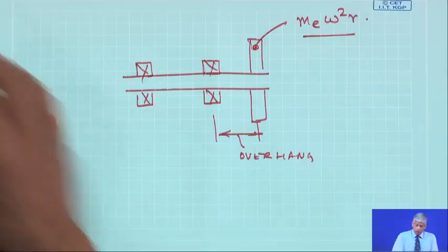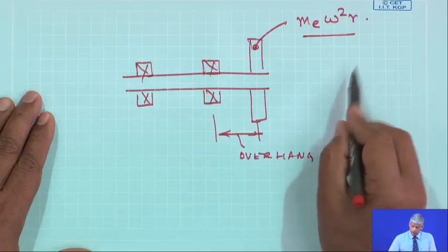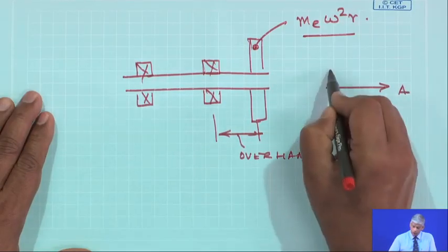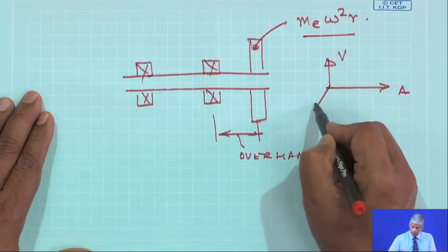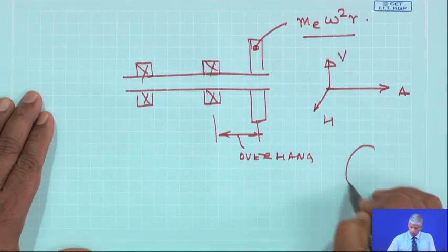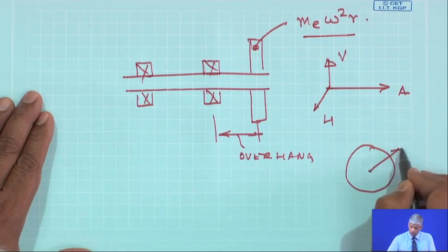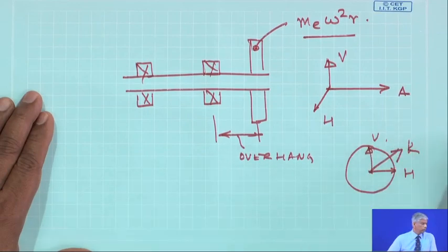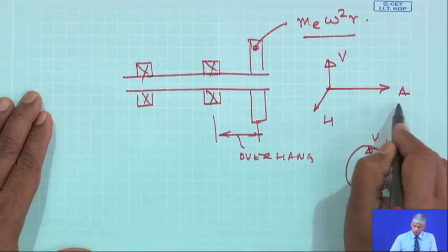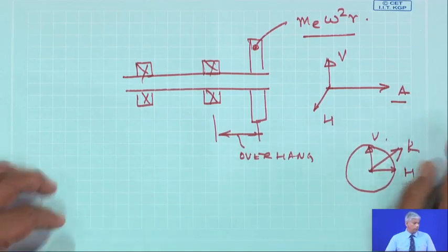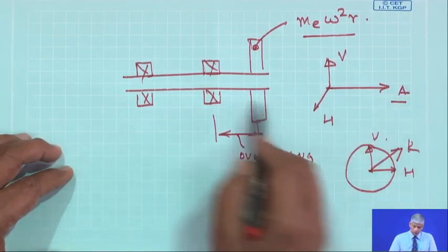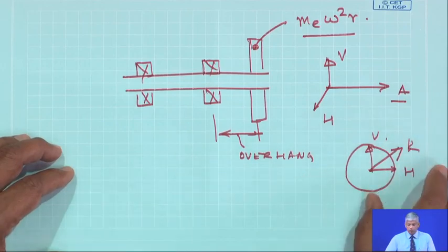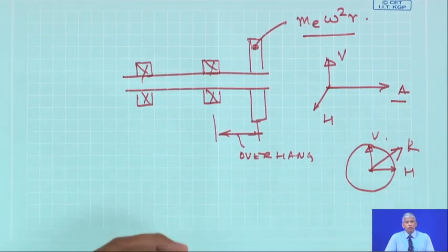Okay. There could be a strong axial along with the radial. So, in the radial plane, I will have H, I will have V. And then axial vibrations may be unsteady because it may not be uniform, and axial phase may be unsteady. If you measure the phase angle between them, this can happen. So, these are some of the scenarios which can happen in machinery condition monitoring.